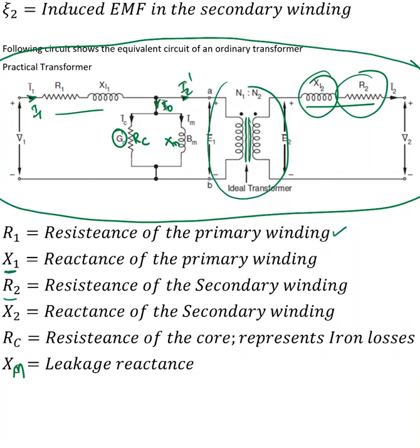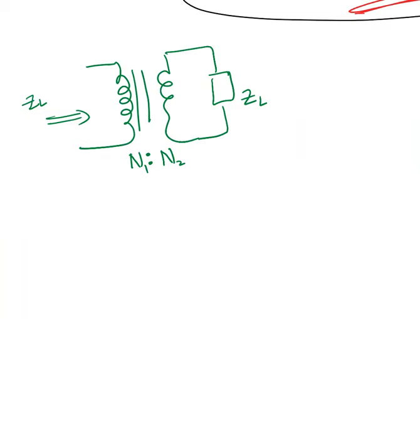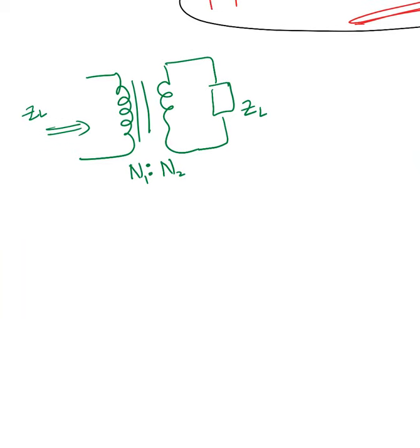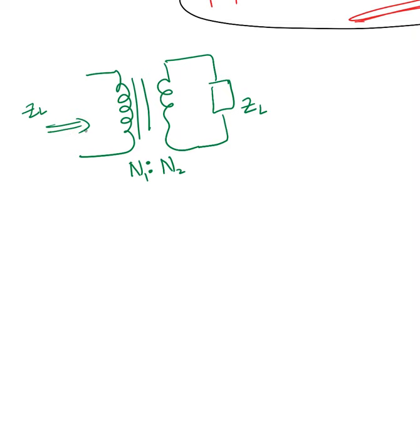Now when we are solving examples, how do we solve for the required quantities? The transformer is a magnetically coupled circuit, right? There is no electrical connection. Then how is the primary winding going to see the load resistance? That's what I'm going to define in this case. I'm taking this as an ideal transformer. N1 to N2 is the transformer ratio or turns ratio, so N2 over N1 is nothing but the transformer ratio. I'm calling that N. Now the Z, instead of ZL, I'm going to call this Z input.